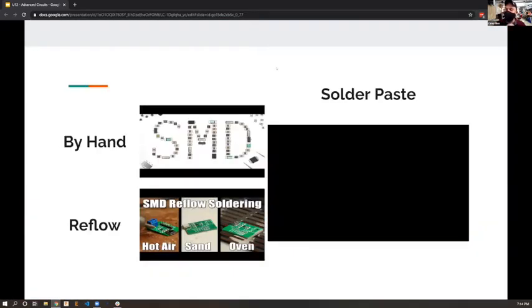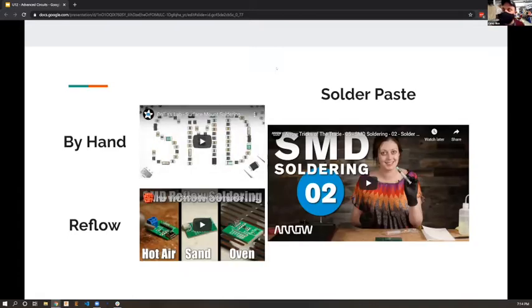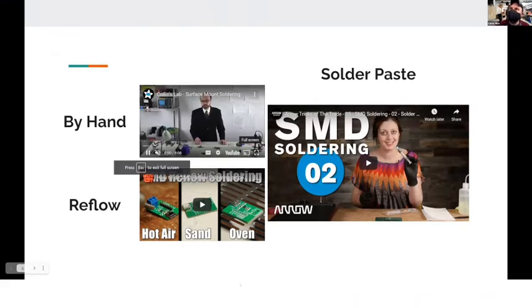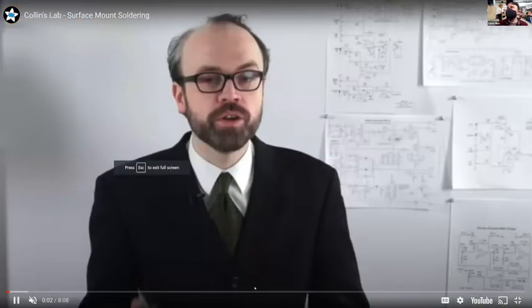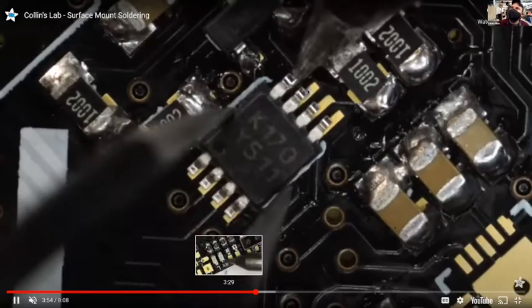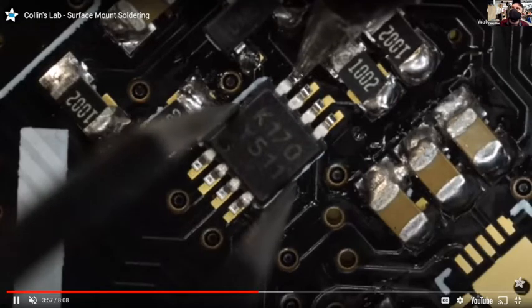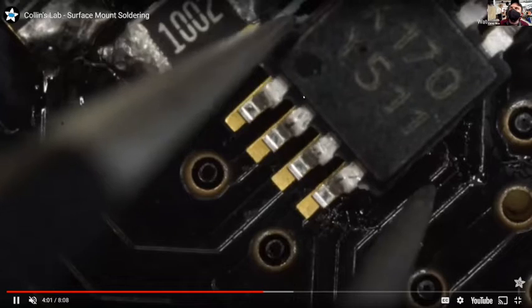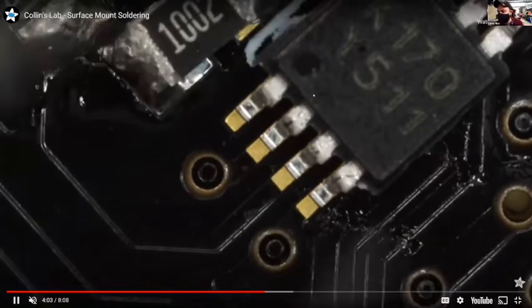These 3 videos I would solidly recommend you watch. They're each good in their own right, and they've all got good tips. This is, let's see, Colin's lab, we can pull up this scene really quickly, where he does a lot of soldering by hand in this video, and so you can watch him go through the process of holding it with tweezers, moving an iron in, using things to get all these pieces aligned. It may look tedious and small, but it's not too bad.